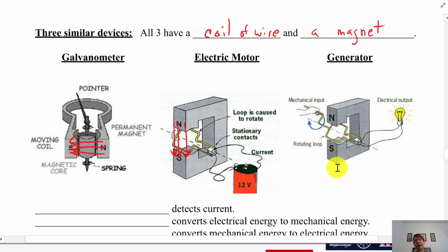And the generator is just the opposite of the motor. In fact, you can have these two things almost be interchangeable. There are devices that can work both ways. But we're not going to do that right now. But generators basically are totally making use of Faraday's law of generating electricity. Once again, it's very easy to generate electricity. You just have to move a magnet or spin a magnet or spin a coil of wire by a magnet. Move your conductor, spin your conductor by the magnetic field.